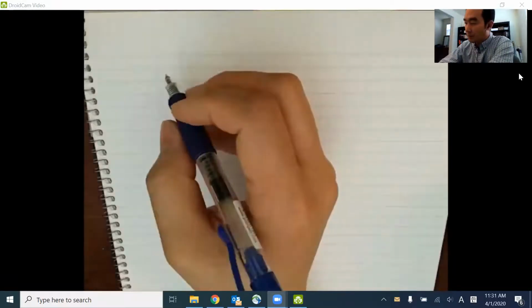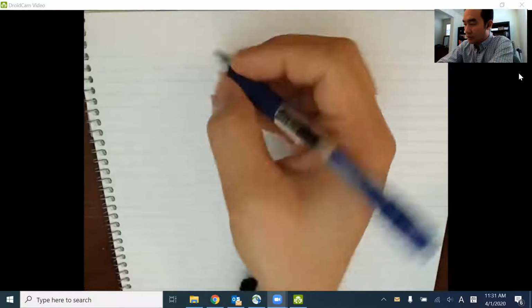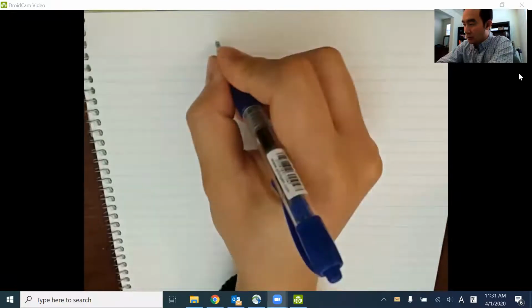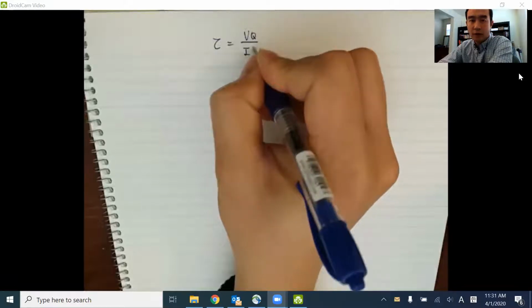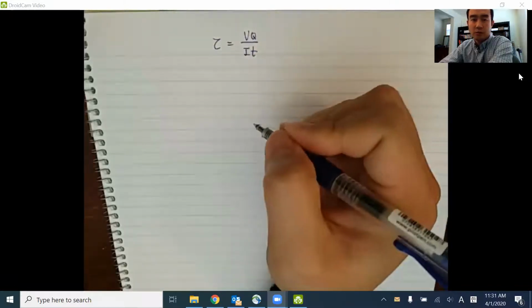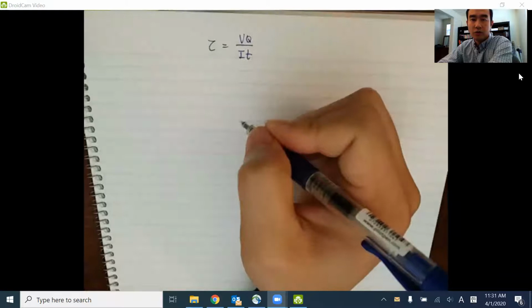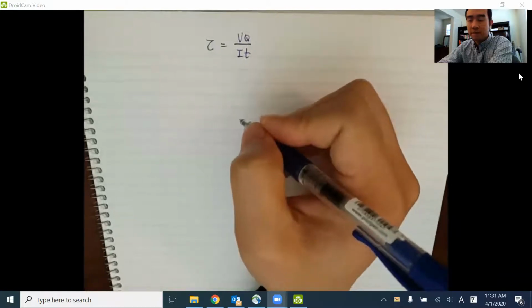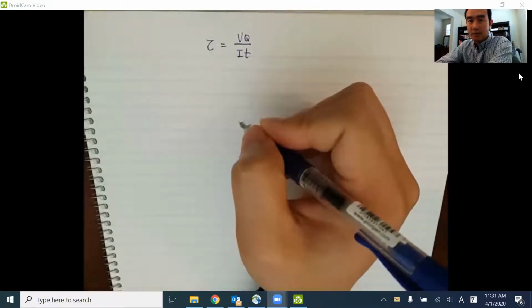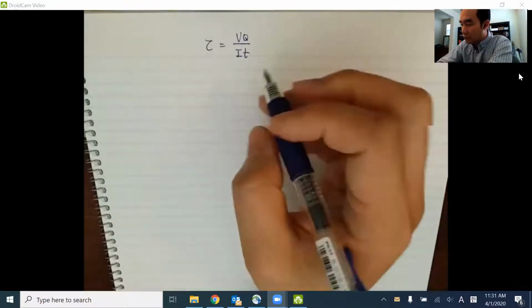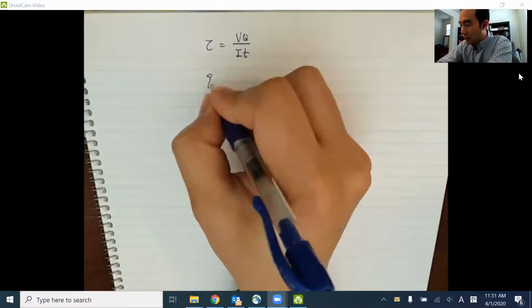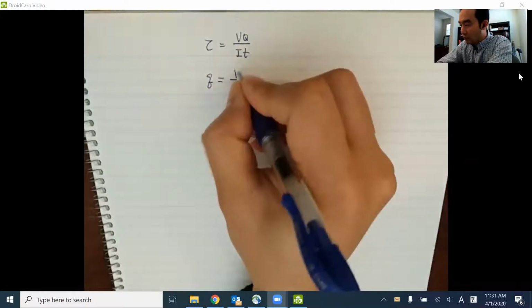Okay, so the first part we had discussion on the shear stress, which is tau equal to VQ over It. So whenever we have a shear force, we should be able to find out the corresponding shear stress using this equation, right? The other concept in the last part of chapter 12 is shear flow. So shear flow q, we can calculate it as VQ over I.